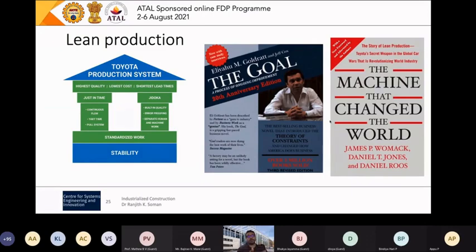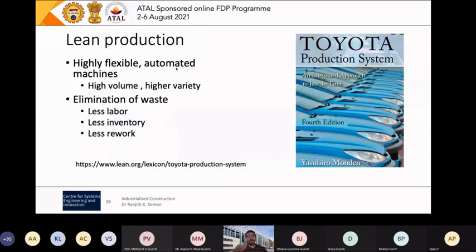That process is called value stream mapping, and they categorized each of the methods that were non-value adding and started removing them. They also increased the points of quality checks, and that reduced errors. So mass production could produce a lot of things in a really short time, but there was no customization and errors were building up. In lean production, you are still producing a lot of stuff with fewer errors, but we are still not getting a customized product. So that is lean production.